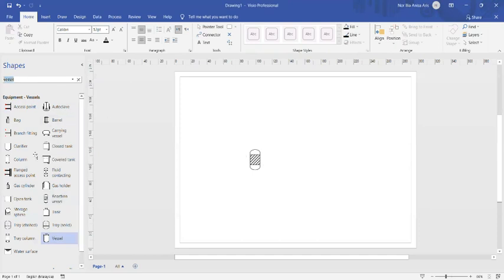Okay, and after that, we have a separator, right? To separate gas and liquid. So I just choose a vessel, the common vessel here. And then we have another one, the distillation column. For the distillation column, you may choose either the column here or you have three columns. In this example, I would like to choose this one. Just drag it a bit so the column is much taller than the other equipment. Okay, these are the general equipment.